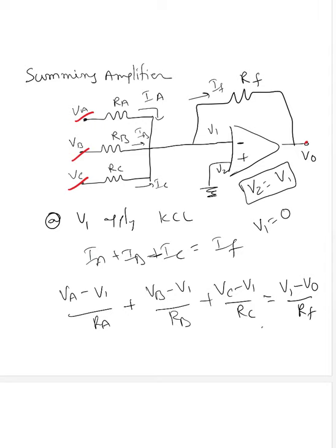Now the basic principle: we know that there is no current passing through this, 0 ampere, and we already know V2 equals V1. So these are the two important points. As long as we understand these two, it's going to be a lot easier, and it's nothing but solving a circuit with parallel resistors or series resistors, something like this.